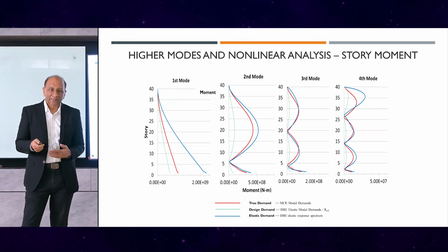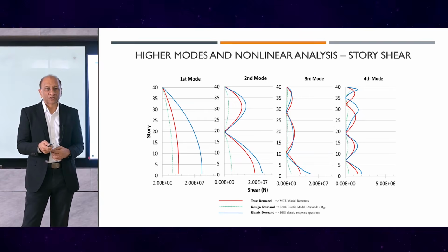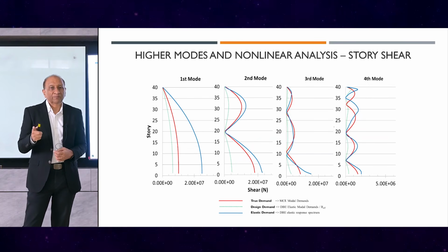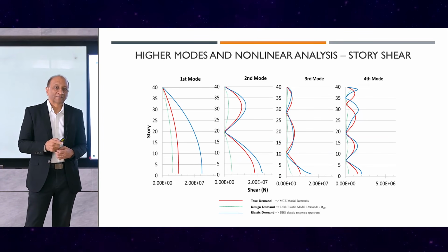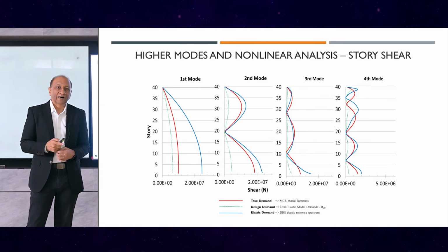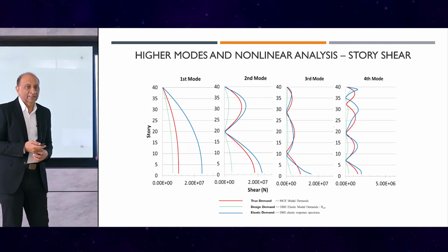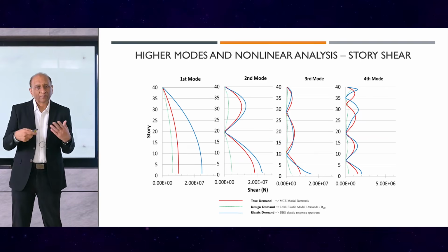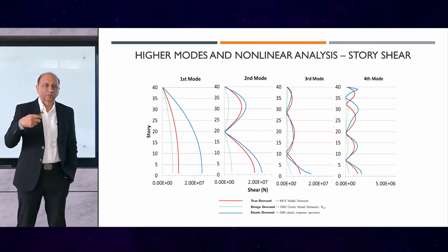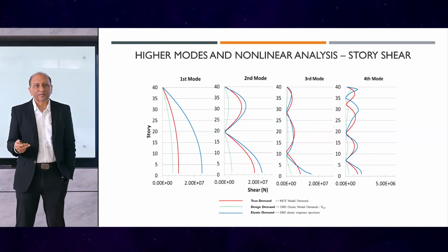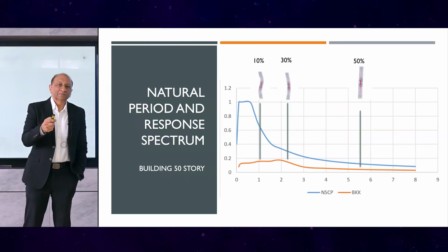So that leads us to believe that the actual shear, especially if you look at the shear in the structure, is much higher than what the R factor, the total response divided by R, gives us. And this could be a cause of a lot of difficulties in tall buildings. So that's why many methods are being revised using multi-mode analysis with partial R or different R for each mode. So this is another subject that we can talk about sometime.